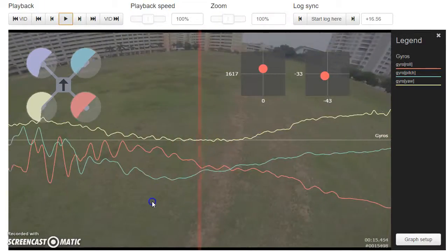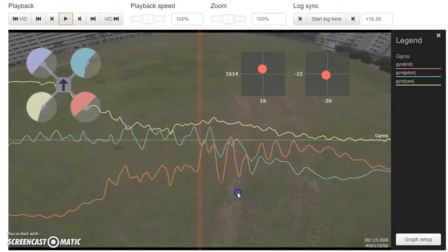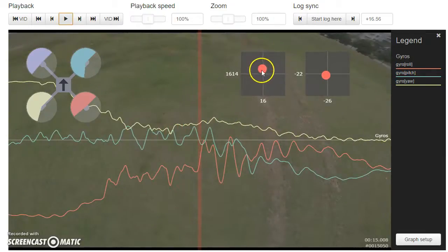there's another, that was a great one. We'll stick to that one. If we go through your video, we can see your throttle is often in that range of about 1500 to 1600. That's often where you're cruising. So if that's where you're cruising, then probably you should be tuning for that with little or no TPA, and then tuning TPA for the higher throttle positions.